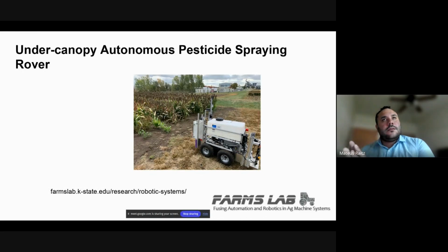So those were questions that we had, and we ended up deciding to use CAN FD as our physical layer and leveraging micro-ROS for the higher level, right? Since we are already using ROS for our system, it makes sense to use micro-ROS, right? But let's talk about why we chose CAN.